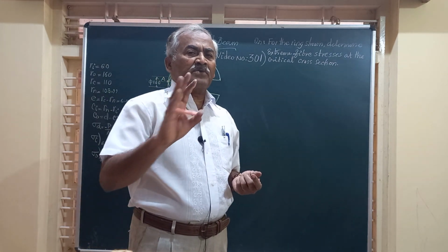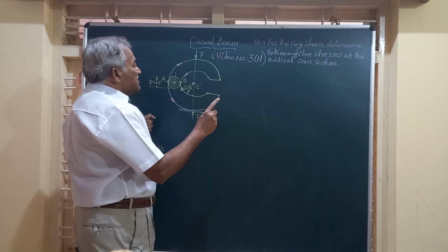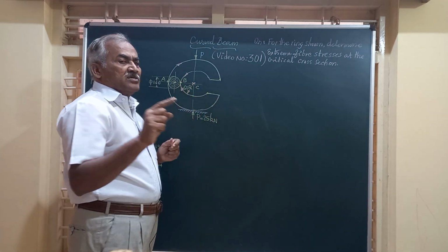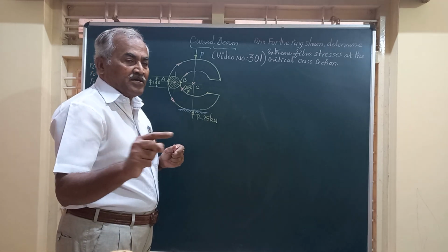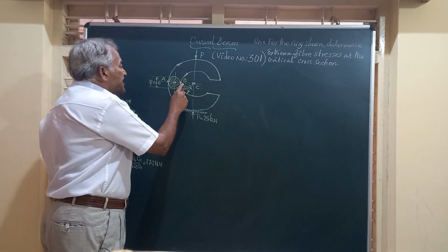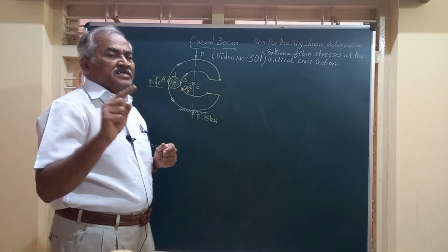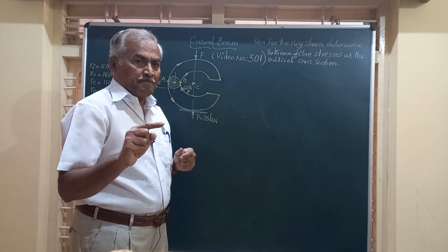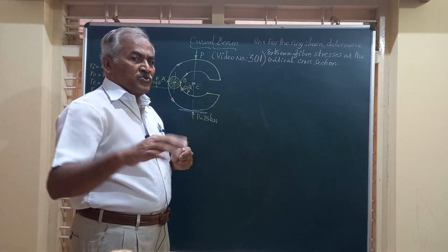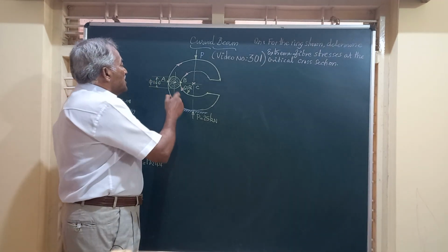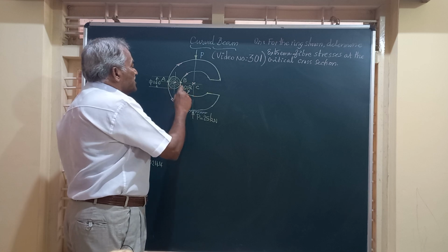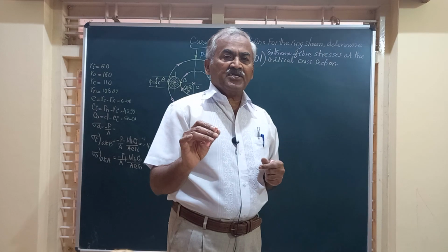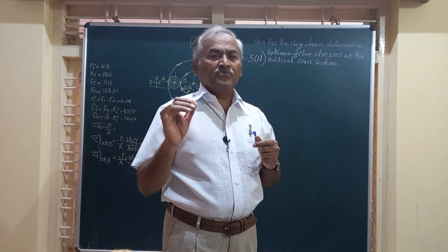So there are two types of bending stress. The normal stress due to bending at the inner fiber, which is called sigma Bi, and the normal stress due to bending at the outer fiber, that is at A, that we call sigma B at A. So friends, to say totally, the cross section AB is subjected to the combined effect of the direct stress and the normal stress due to bending.